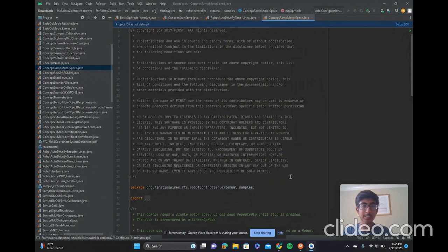Okay, so as we can see here, this is the FTC SDK that we were using for the servo programs as well. So the first thing that I would suggest before you actually start looking into code is on your driver hub, there would be a three button option in the top, and here you click configure robot.